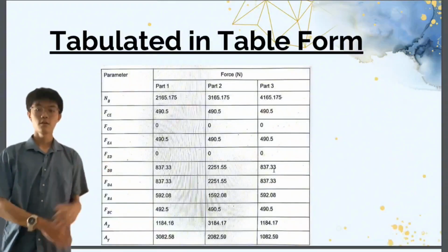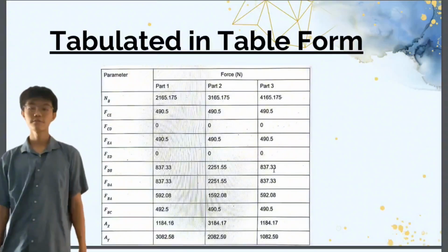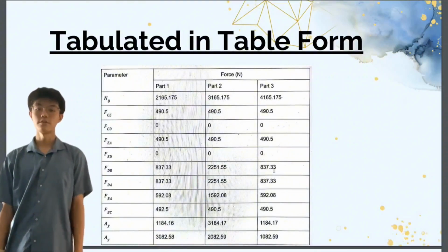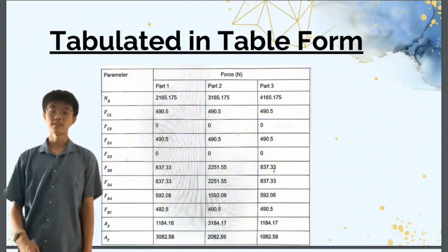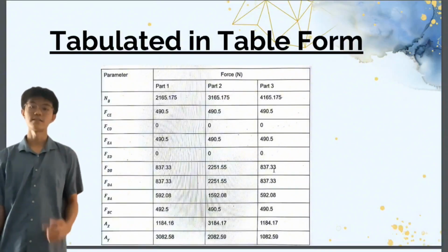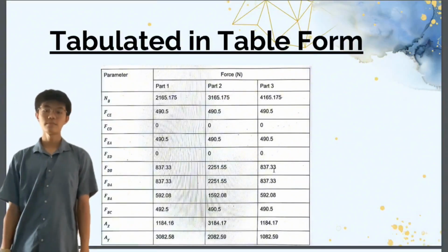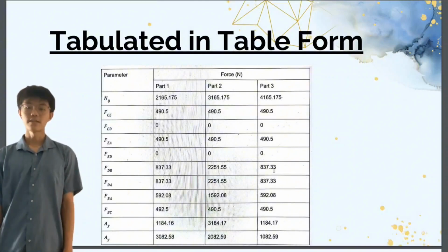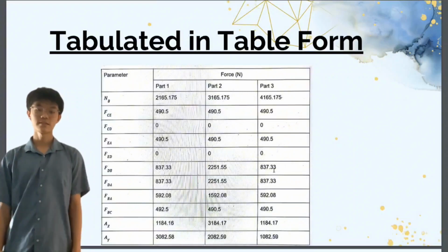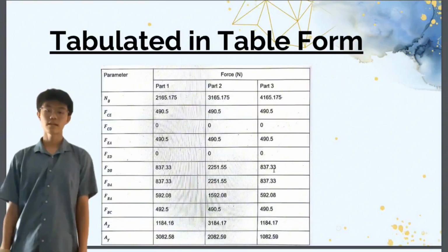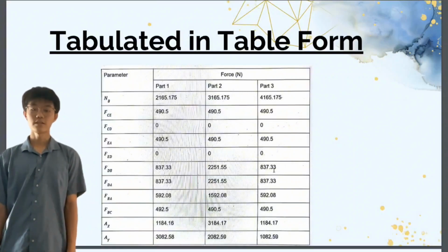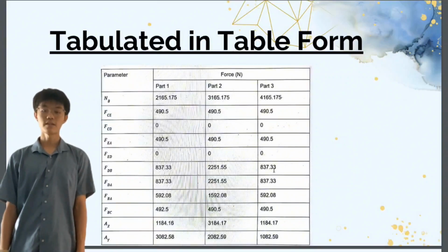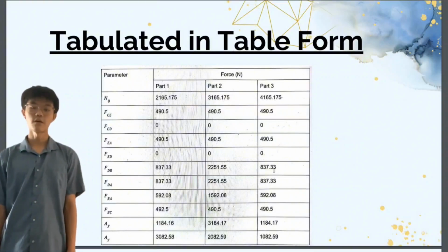So from the table, we can observe that the highest force was sustained by the pin with a recorded value of 4165.18 Newton among all the forces. So for safety concern, this force will be used as the standard value to be utilized in minimum beam strength calculations with an assumed value of 1.5 as the safety factor. In this case, the safety factor is 1.5, indicating that the beam has 1.5 times the strength needed to support the applied load. The minimum strength of every beam will be calculated in order to choose suitable types of material for each beam.